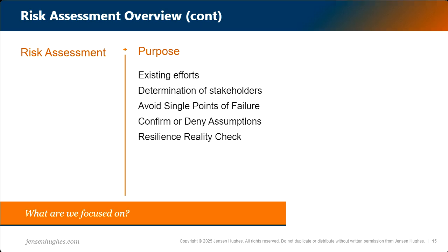With that being said, and to confirm or deny assumptions, once we did our assessment, we determined that easily the elevator and stairwell lobbies could be put on an access control system with door position switches that will alert security of either a door prop open or a breach. But there was the question: are we ceding the parking garage?